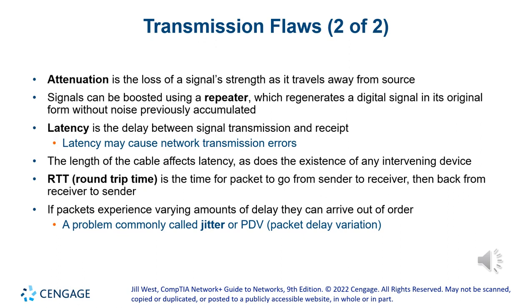To overcome that, you can get a repeater. The repeater will regenerate the signal, which works pretty well. Since the signal is digital, ones and zeros, it could become very jagged as it degrades. But since the timing, that frequency, is always the same, the repeater can duplicate that frequency and reconstruct the signal specifically to the ones and zeros exactly, and make it a nice square signal without the errors.